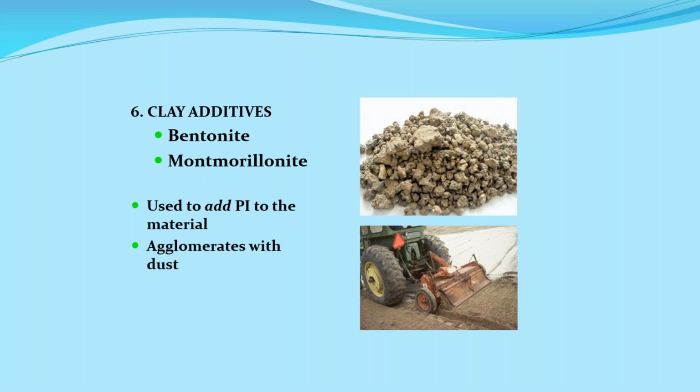A lot of those organizations that I've worked with over the years are currently using the bentonite. They mix the bentonite in, and then once they lay the gravel back down on the roadway, they actually treat it with a mag chloride to make sure the bentonite stays in that roadway. It doesn't turn into a powder and get blown off that roadway. So that's another type of treatment that you have available to you.